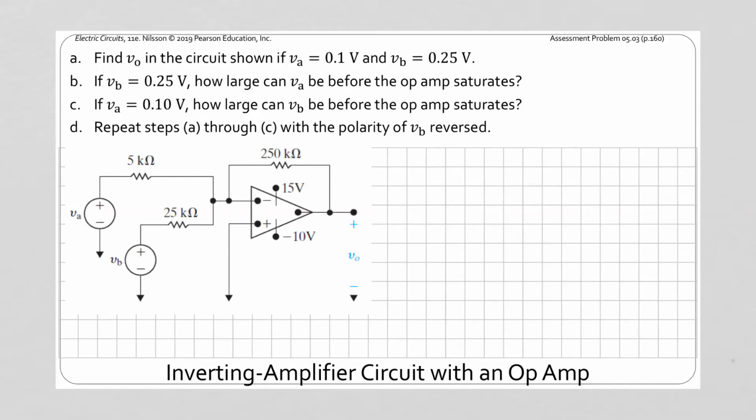Here we have an op-amp that has a feedback loop to it, and so if it has a negative feedback loop, then the op-amp should be in the linear region, and that tells us that the voltage at the two terminals should be the same. Here the non-inverting terminal is connected to ground. This is a 0 because this is our ground, and so it tells us that this other terminal here should also be a 0, and in fact that is going to extend to everything else.